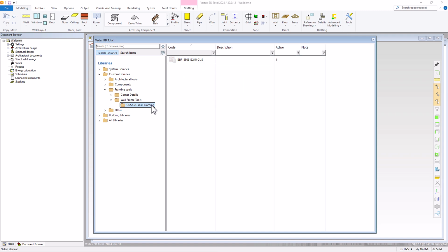Next, we're going to add a new layer. This is not a necessary step if there is an existing layer or material type. In this exercise, we're going to take the process a little further. Let's create a layer for a made-up manufacturer's sheathing panel. Let's say there's a new sheathing panel from company ABC that we want to add to our Vertex library. The simplest method for adding a new layer is to create it by copying a similar existing layer and then editing it to what we need.